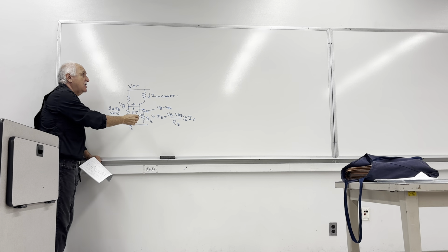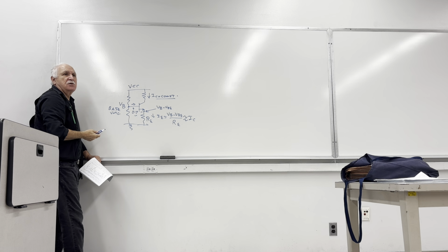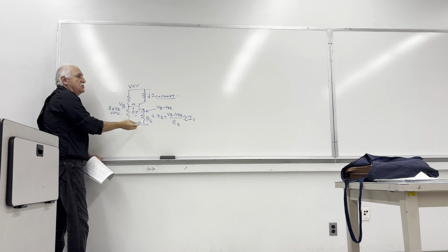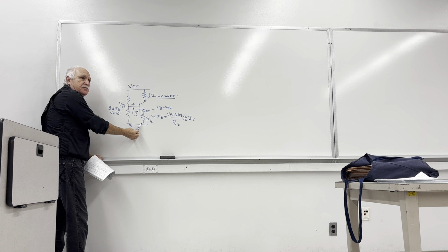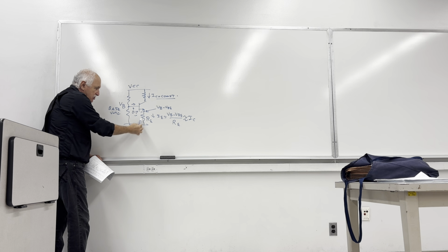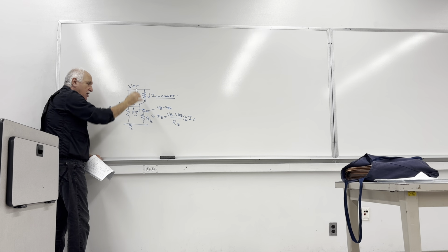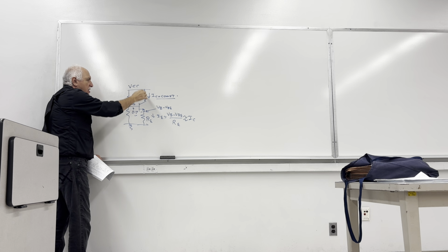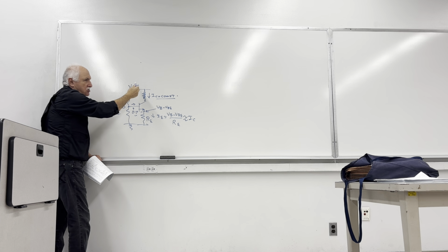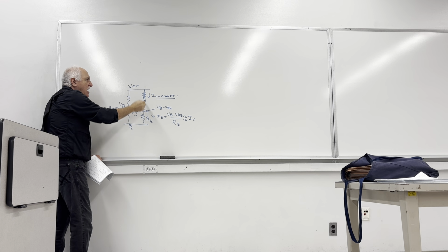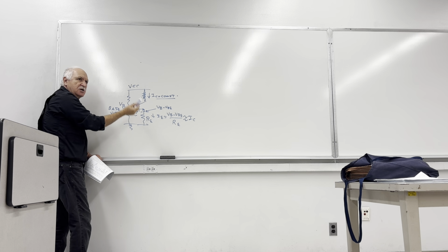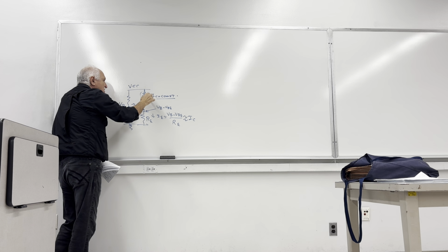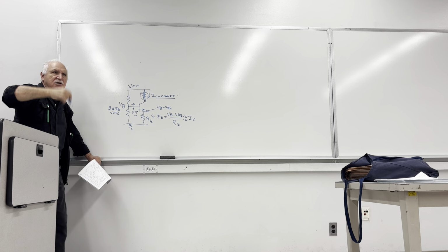So we can generate a constant current here in the collector path. In other words, if I short it, there will be no change in the current there, because the current is dictated from here. So this is how it was established. It was the emitter current that established the collector current. So if I short that, currents stay constant. If I take it to a more positive voltage, it should stay constant. If I bring it a little down by putting a resistor, provided I don't saturate the transistor, still it is a constant, you see? So this is actually a constant current source, that collector path.